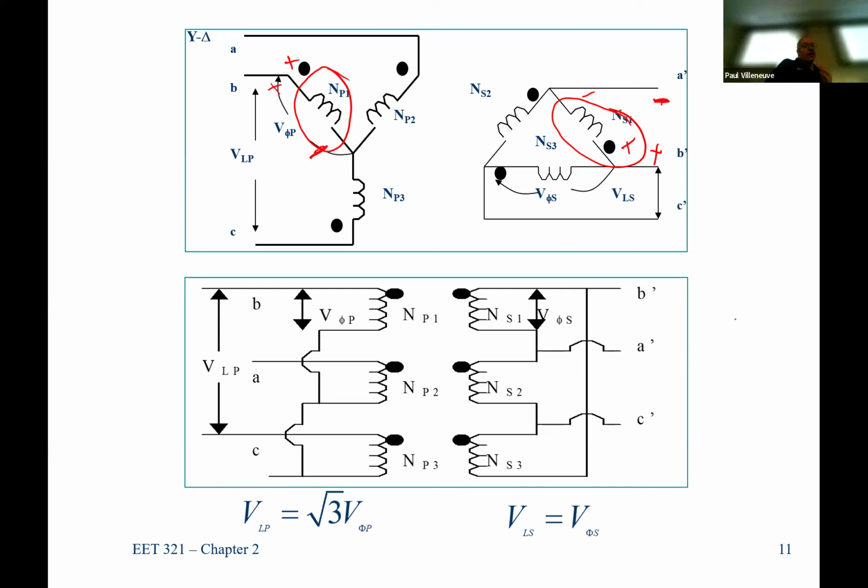Because one of the things that really gets confusing when you set up 3-phase transformers is, hey, I can put A, B, and C here, but there's nothing saying I can't switch A to B. I can move B to A. And now I have to be very careful, because that A may not be in phase with the A that comes in on the inside. So one of the things that's hard is transformer phasing, and it can get really confusing because it's just a utility that picks, this is phase A, this is phase B, this is phase C. So they pick phase A coming in, and then when they go to a transformer on the way out, they pick phase A, B, and C.